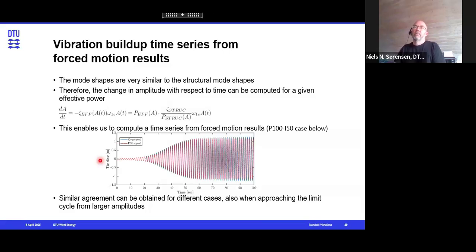We also developed a small model based on the similarity between the structural modes and the aeroelastic modes. Based on the modal description, we can derive a small model that can predict the time development of the amplitude when we know something about the aerodynamic power, the structural dissipation due to damping, a damping coefficient that we can extract from the modal model, and the vibration frequency.